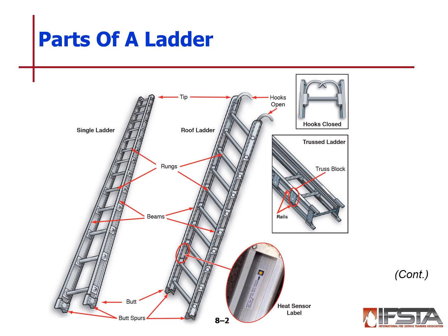With the parts of your ladder, we have two different types of ladders. We have straight ladder, roof ladder, and we have extension ladders. With the straight and the roof ladder, the only difference between those two are the hooks at the tip. So we'll start with the tip end. The tip will have, if it is a roof ladder, the hooks that fold out and lock in place.